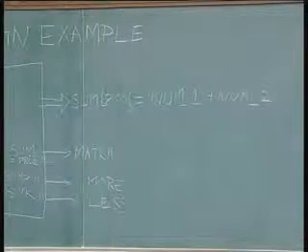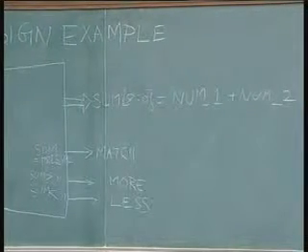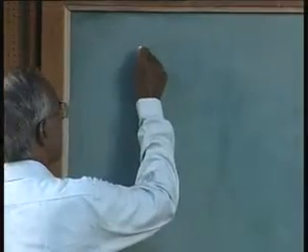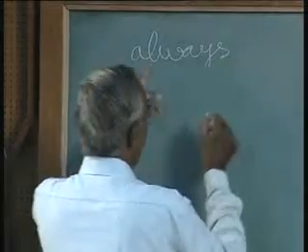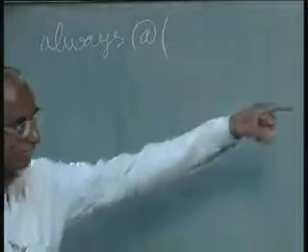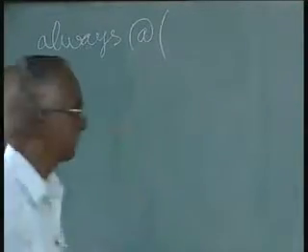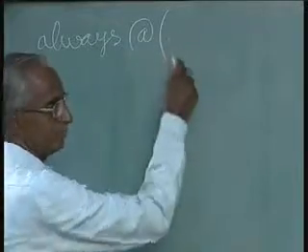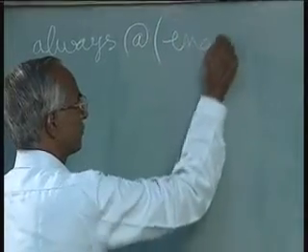We can use assign statements for this, but however, the always statement is a better thing because we need to take action only when there is a change in the inputs. So we'll use the always statement as such. So first, in this always block, you say always at, this is mandatory, and list all the input variables. You should always speak in terms of signals, not variables. That is a C habit, right? So I'll just list this enable sum and all the inputs.